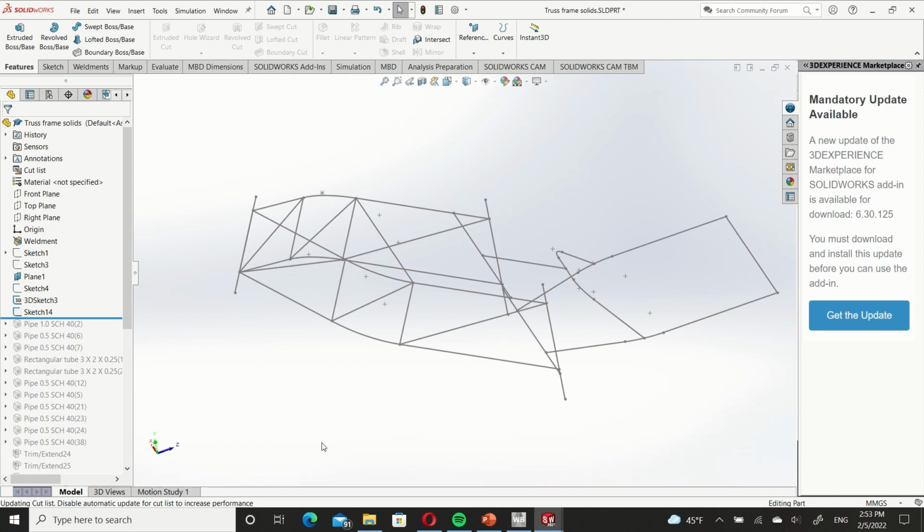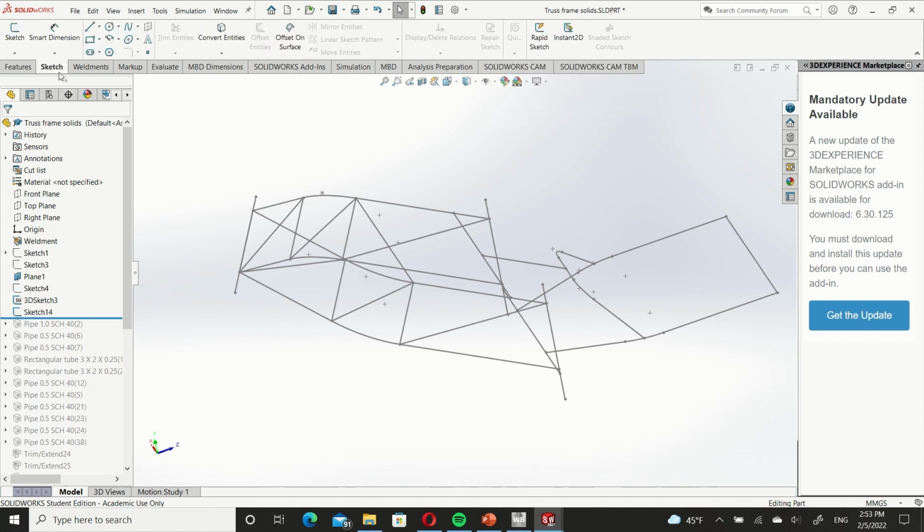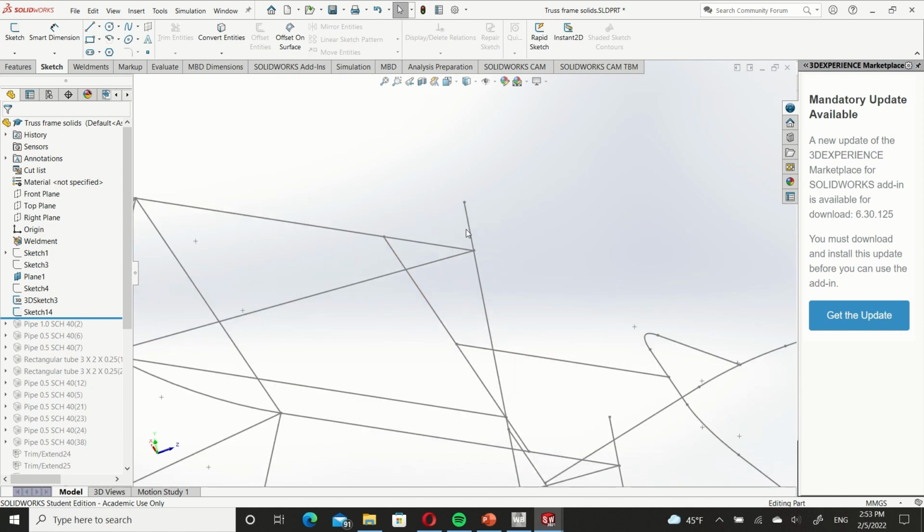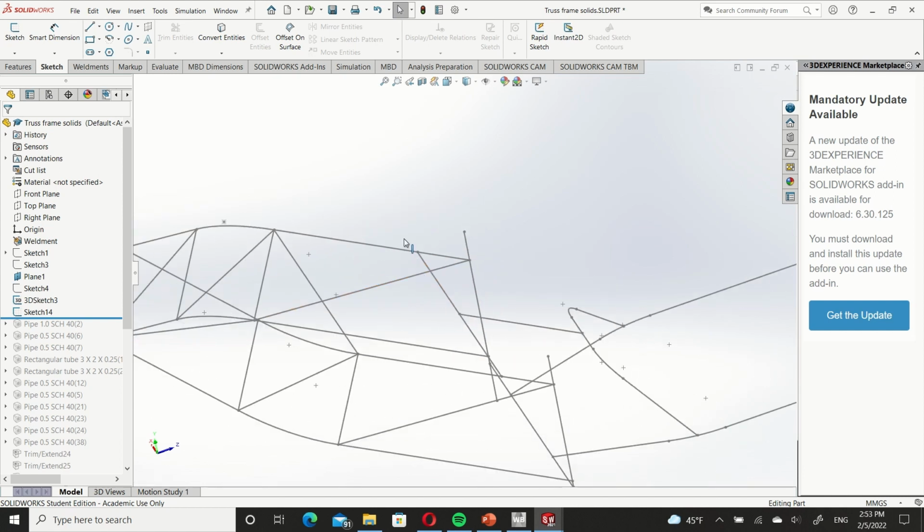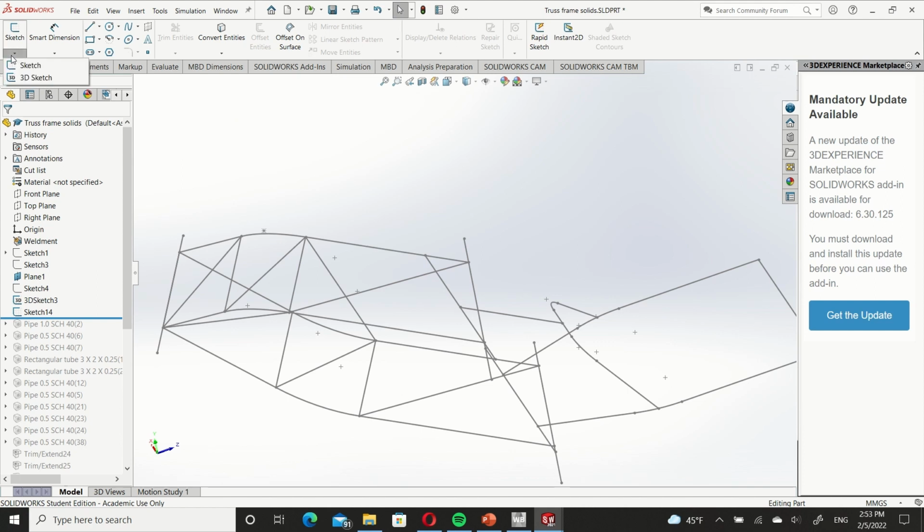And we're going to want to turn this into a bunch of curves. ANSYS does not accept simply sketches, you need to give it curves. And the way to do this within SolidWorks is to make composite curves. And composite curves also do not like disjoints like this. Like this will not fly within composite curves in ANSYS. So you're essentially going to have to convert the entire model into a bunch of smooth curves within sketches. See, we have a nice smooth one right here. Let me exit sketch.